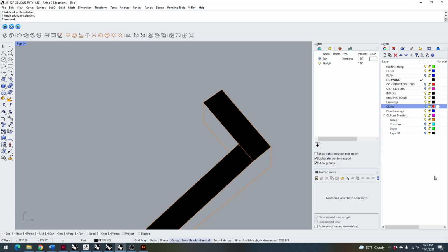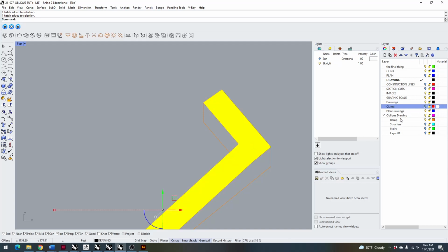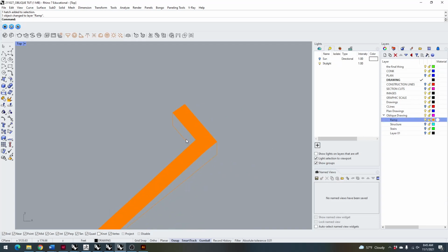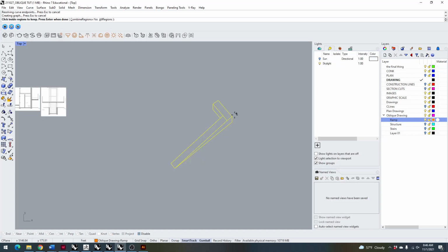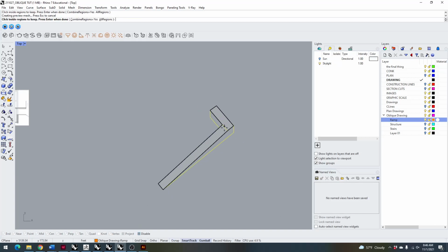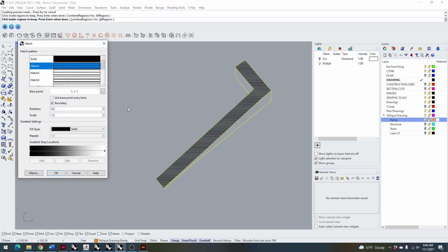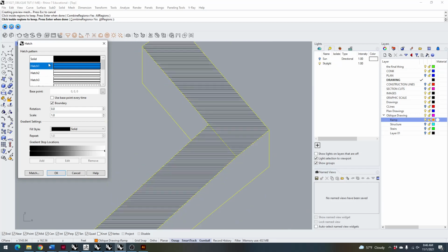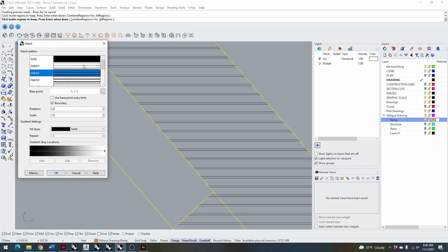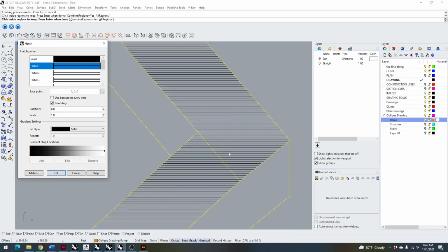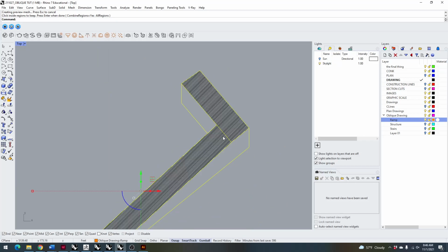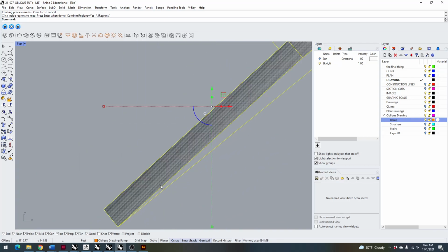And the color can be determined in the layer. It will display as the color of whatever layer it's in, but it can print to a different color. So that's one thing. The other hatch I'm going to cover is 45-degree lines. And so selecting in the region that you want to hatch, after selecting close regions of lines, you can select your desired hatch. I like this one. I like the spacing of it. It's just evenly spaced singular lines. And you can specify a given rotation, so that is a 45-degree rotation there.